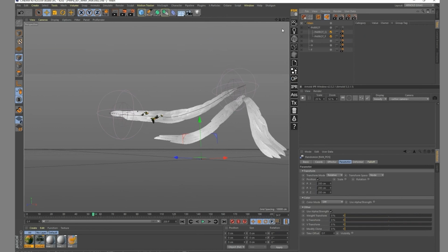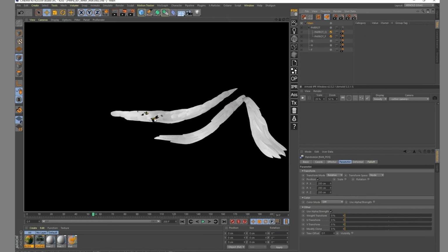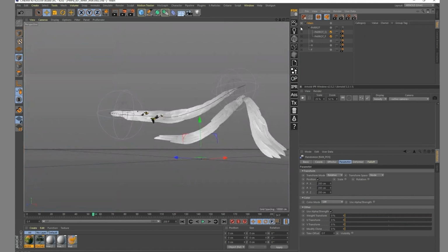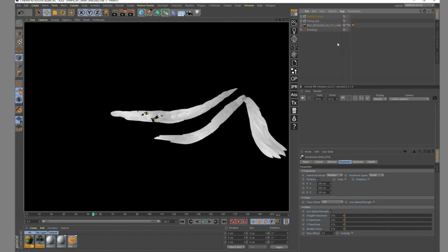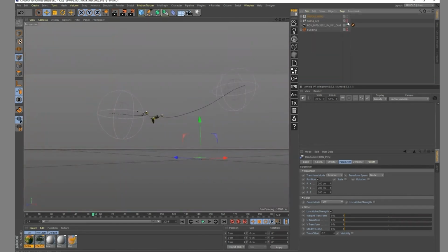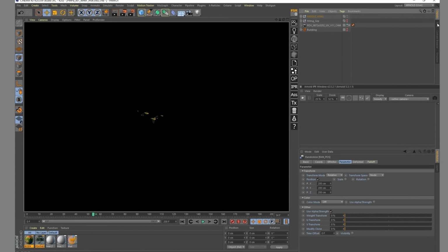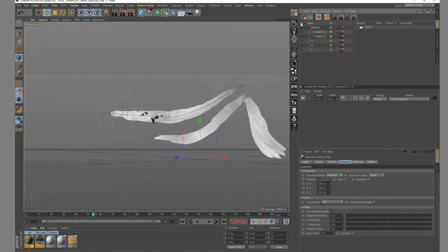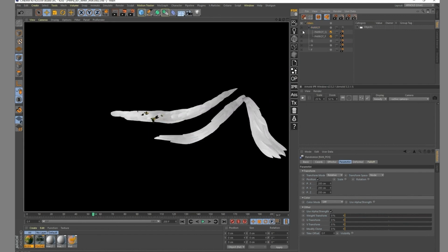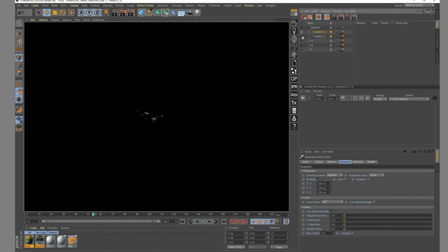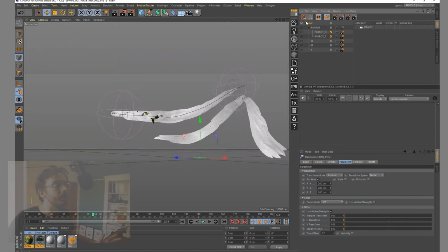If I'm rendering a frame right now, I can see at the same time the parrot and the background. I don't want those wings to be seen, so I'm going to activate the auto take system. I'm going to go inside of the main one of the parrots, check it's still seen, and I'm just going to deactivate that. And right now, only for my parrot, I won't see anything more from that size. So that's fine, working for me. I can render my parrot at quarter res way faster, work with them, and then render the full res when I need it. That's one of the first parts that we're going to do.